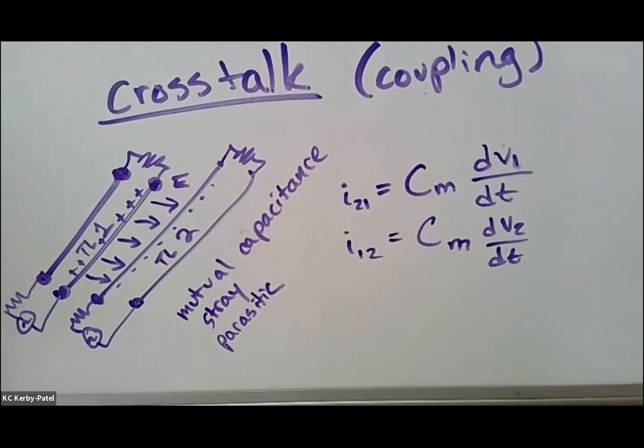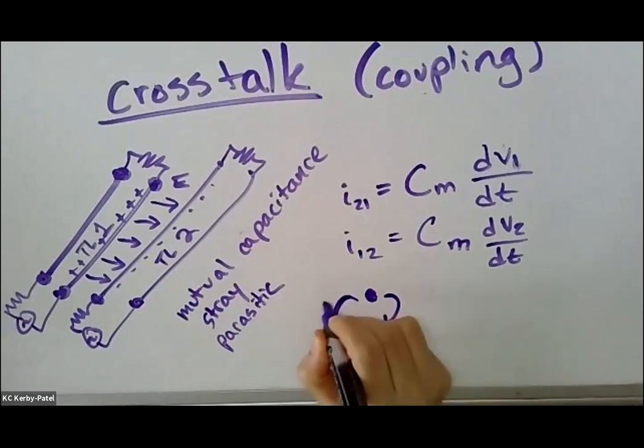That is the situation. I've seen the YouTube videos of people demonstrating that. You end up with a mutual capacitance or a mutual inductance developing between your fluorescent light and the power lines above. And the power lines have really high voltage. So there are really strong electric fields around there. And those electric fields are not completely confined between the two power lines, right? Because you've got lines that are like this, and the field is doing one of these.